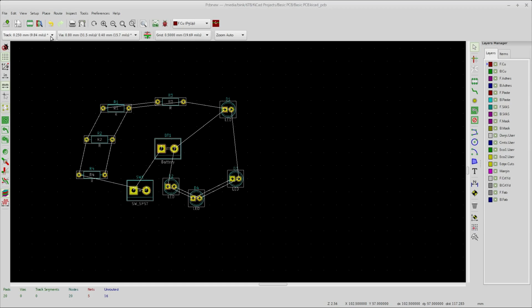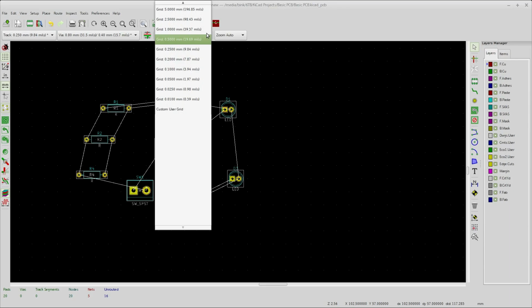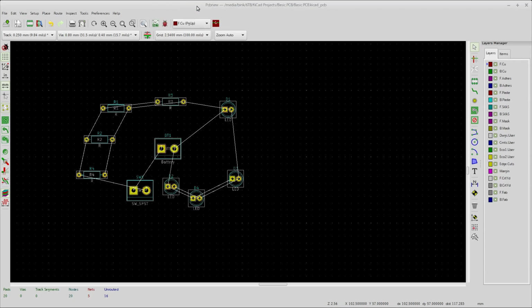So I'm going to go over here to our track and, or sorry, not to our track, our grid, and I'm going to change it to, how about 100 thou? They say mils, say thou, 100 thou spacing. And then I can start drawing the line for the edge cuts. That's the thing you want to remember. So your edge cuts down here, this layer, again, we have not done a video yet on specifically the layers, but edge cuts is, if you hover over it, says board's perimeter definition. So it's where they're going to cut the board out.